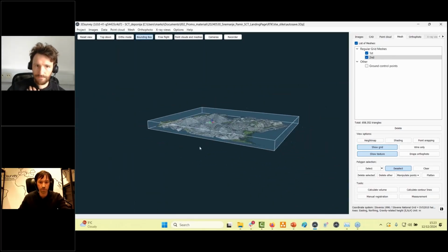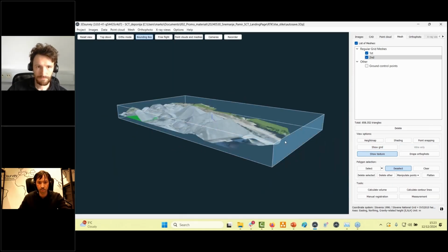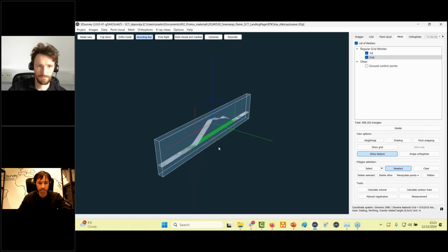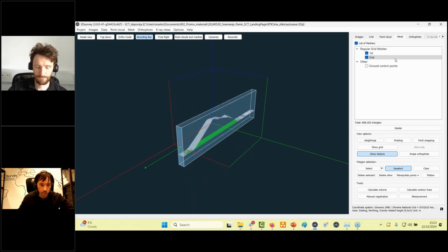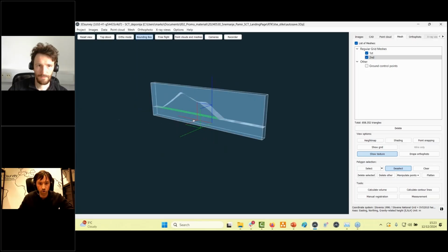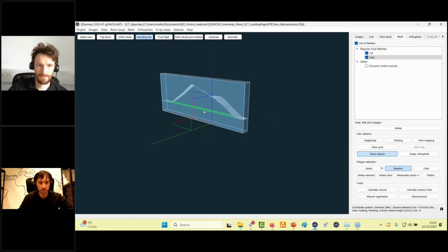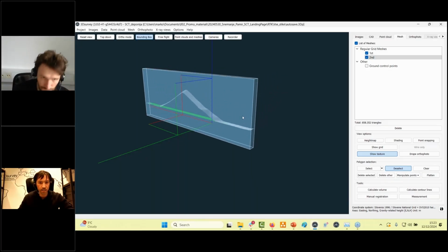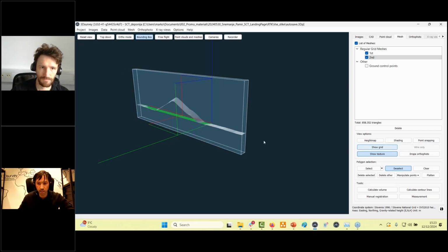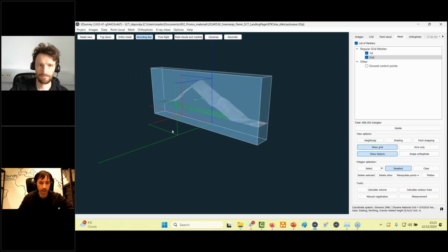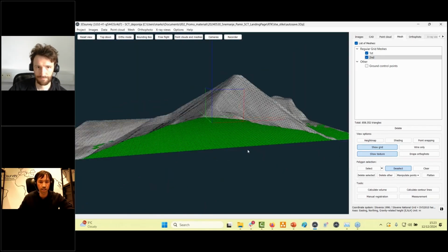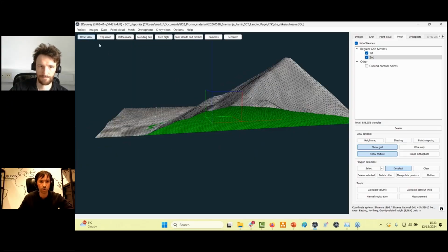Now this is the easy scenario, but sometimes it's super difficult to see a small part of the vegetation or side or anything like that. And in this way, I can really see what my volume actually is. So let me play a bit with the bounding box. I'm using the right mouse. If I use the control button and right mouse click, I can slide down my stockpile and always see the upper and lower surface really nicely. So in this way you can visualize perfectly and you see where the two surfaces come together.